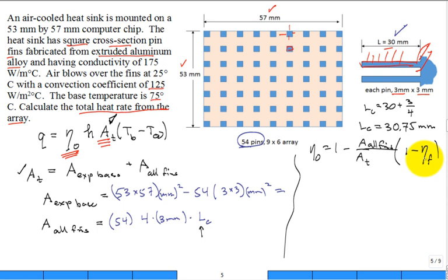All right, in case you're going to chase some numbers on this, I think I have some numbers. Let me see if I can find them. So what is the area ratio? All of the area to the area total. I think it comes in at 0.8873. 88%, 89%. All right. Now I have to work on the efficiency of one fin.